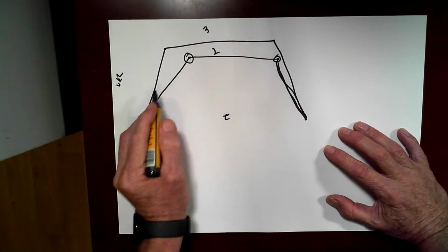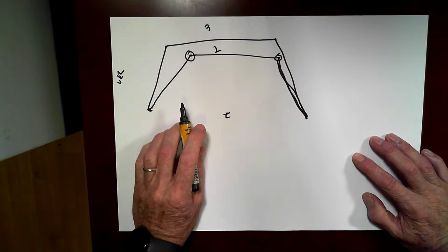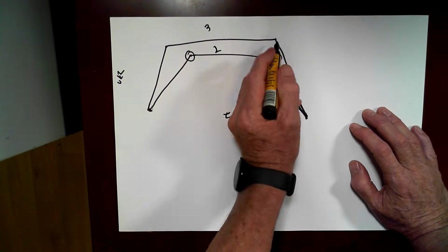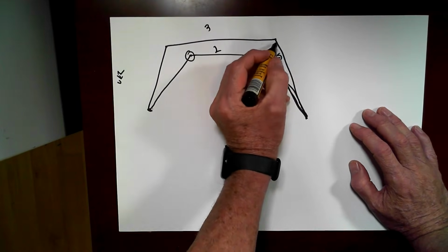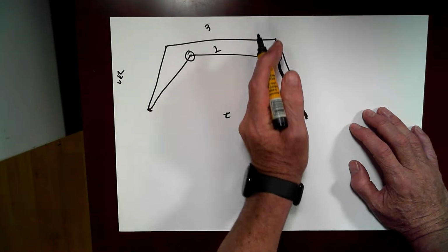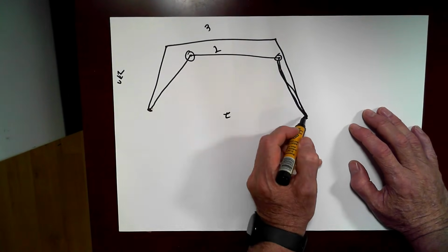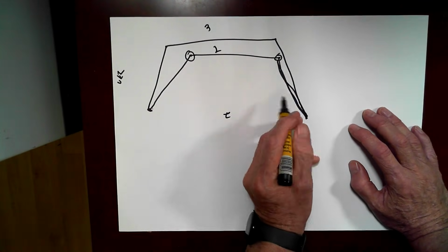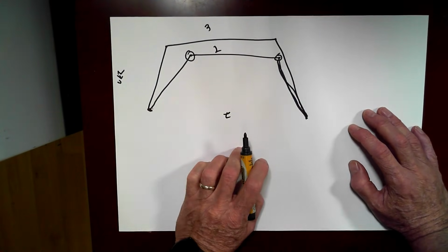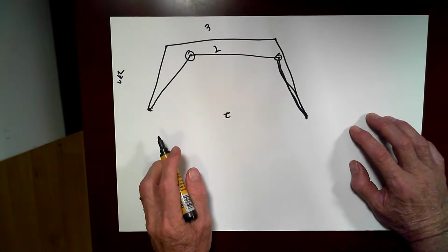But what's happening is that you can't do that because the inertia in the machine will need to be accounted for. And what I've found is that it's this piece here, where you've got a mill with a heavy table, and as you stop, maybe on homing, then the inertia overruns the motor's ability to decelerate, which requires the same amount of energy as it does to accelerate.